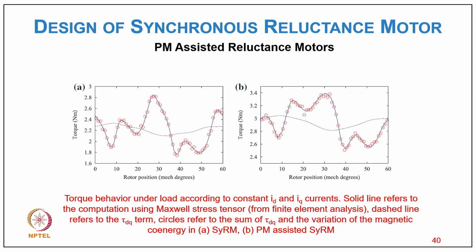And you can see now torque behavior typically with the rotor position and with the mechanical angle in the two cases, PM assisted and without. So you can clearly see there is an increase in torque produced because of PM, I mean, even while maintaining the same stack length.